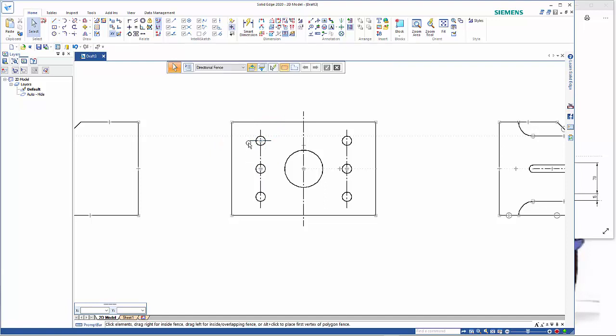and then I can use the move command. So if I highlight it first, go to move, click on copy, go to center point of the line, and just drop that in like so. Escape out. Again, hold the control key down to select multiple, go to copy and move that across.